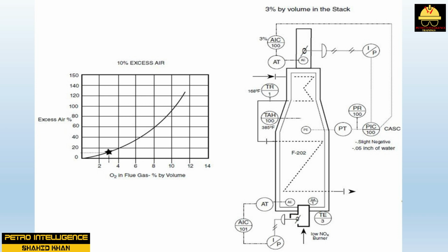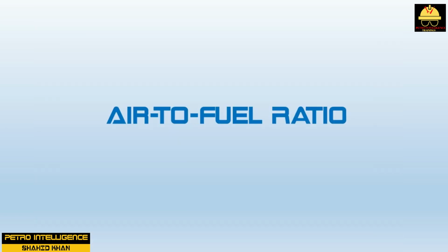Air can enter the furnace through open peepholes, leaks in furnace casing or joints, damaged header box doors and gaskets, and burners that have gone out. It is important to recognize the position of the measurement, either near the burner or in the stack. Large leaks in the furnace can indicate high levels of oxygen in the system.